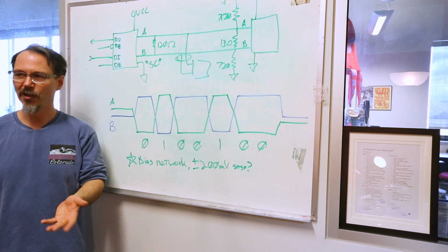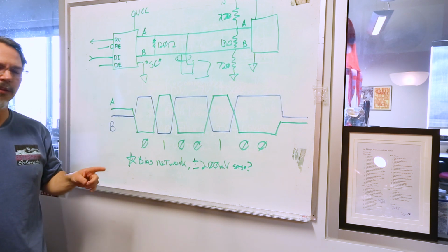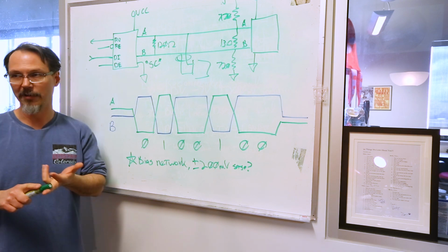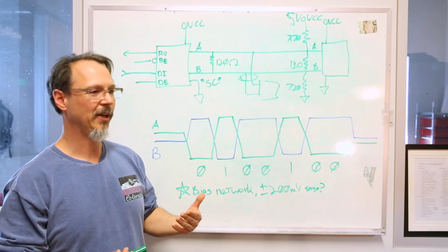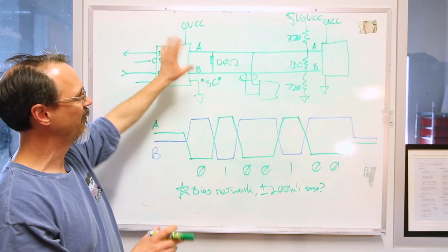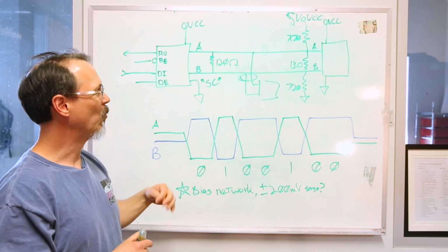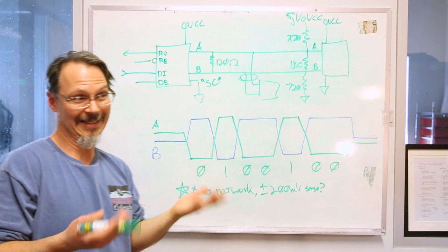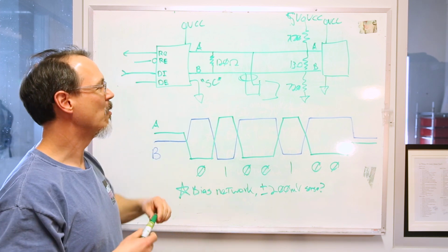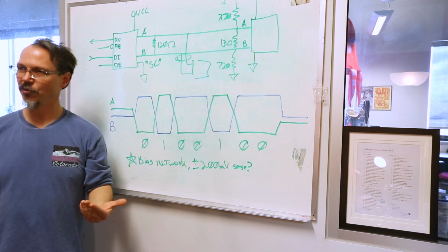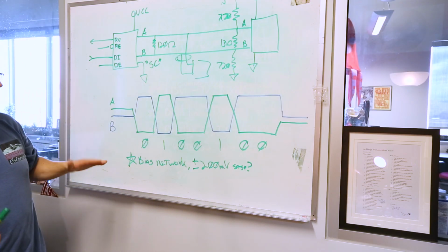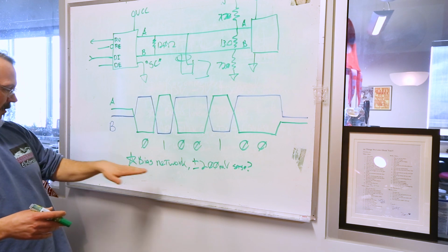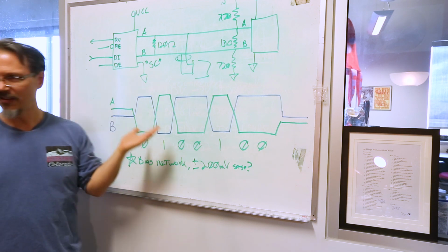Now, there's another tutorial that I'm going to refer you to at the end, and I'll include a link in the video description, written by Renesas, and it's a good tutorial. They do favor Intersil parts, which is fine, but in it you will read that some parts are able to account for all of the biasing without the addition of the resistors. I'm not certain how common that is, but it's seemingly available. So whether or not you're setting up a bias network is going to depend on your choice of transceivers. And I talked about that 200 millivolt sensitivity and the bias network.